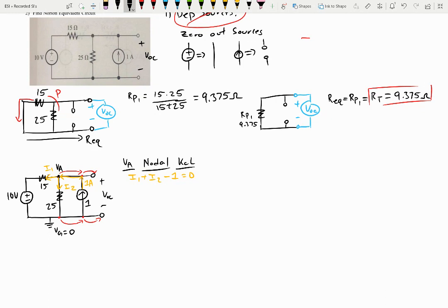Okay. So something that we need to know is right here at this point, that is going to be 10 volts from this battery because we're down here at 0. We're going to travel up through this battery, pick up 10 volts, and end right there with 10 volts. And then we're going to cross over this resistor, and we're going to lose a little bit. So now what we'll do is go and fill all of this out.